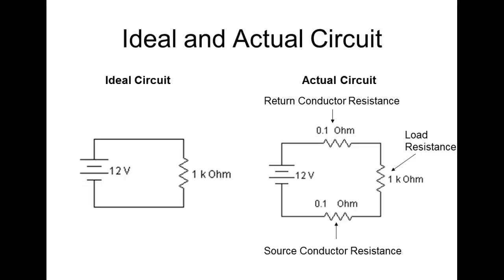But when you deal with people that have to deal with conductors that are miles instead of inches, then there's no way in the world we're going to get rid of R, right? You understand? So with transmission lines, we're really concerned with the R of the line. And even us, if I'm running a light that's 400 meters away from my house, then I'm going to be concerned with the R of the wire, right? And of course, I could use a big wire, but what's the problem with that? What are we shooting for when we size these conductors?